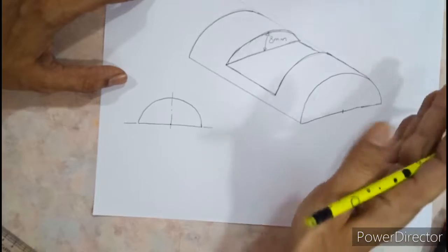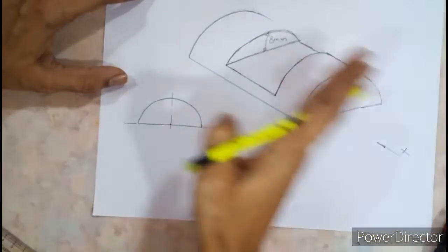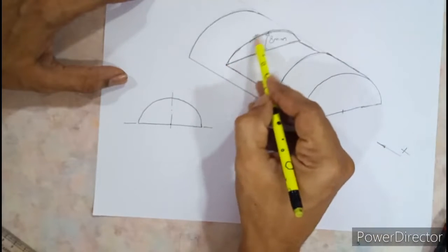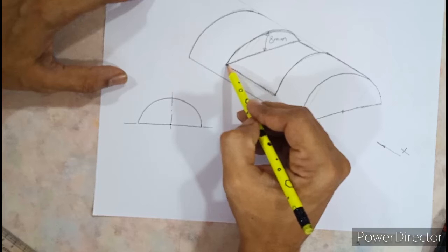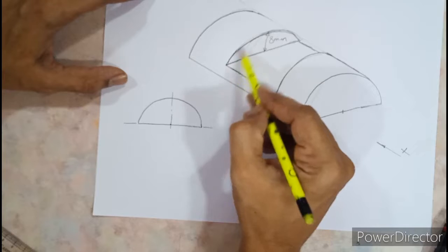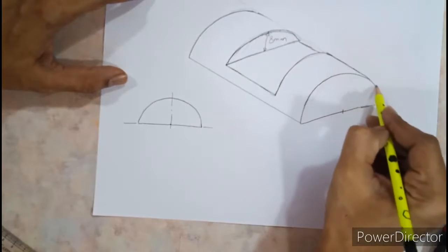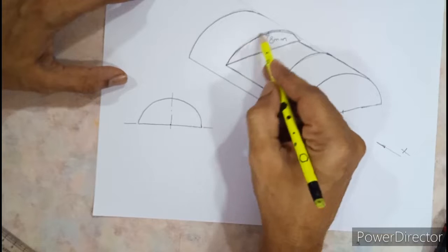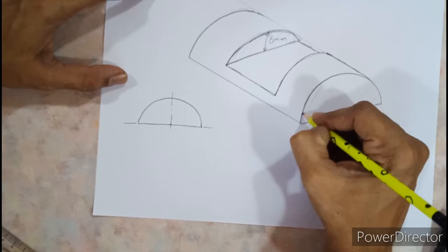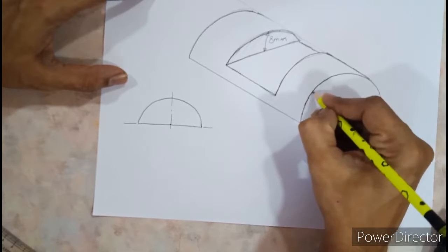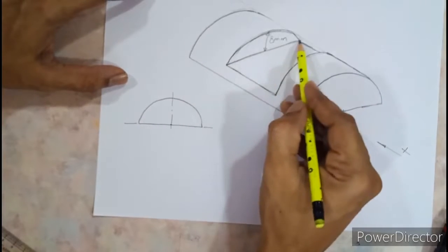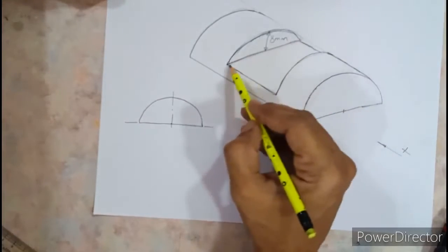If you carefully compress the object like a sponge from this side, then you cannot see this arc of the sector. The arc over here overlaps with this front arc. So if an edge overlaps with the front edge, there is no chance of drawing a hidden line on that dark edge. If I ask you to draw a hidden line on the dark edge, it is meaningless. So you can't draw. But this horizontal edge cannot be seen from the front.